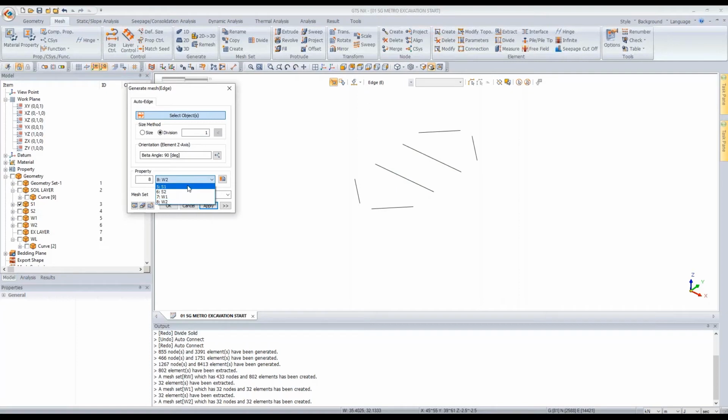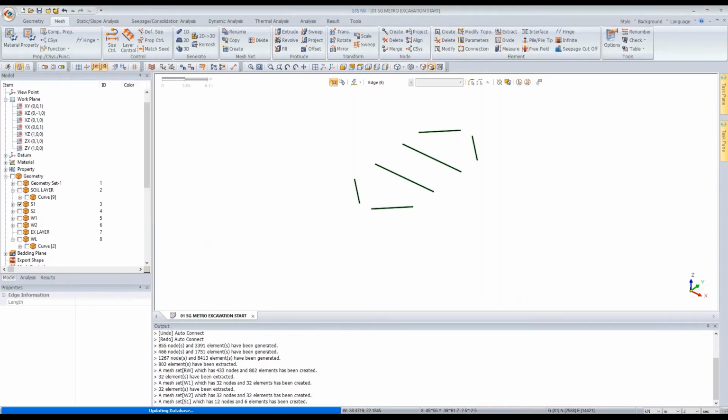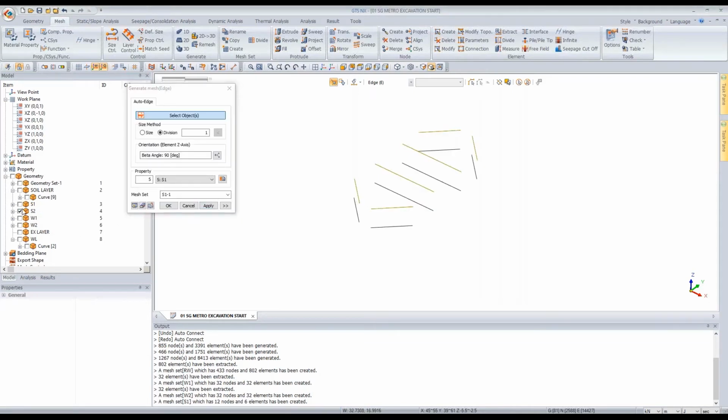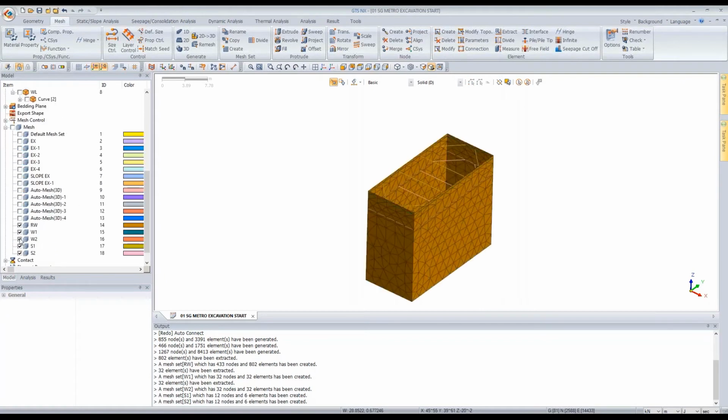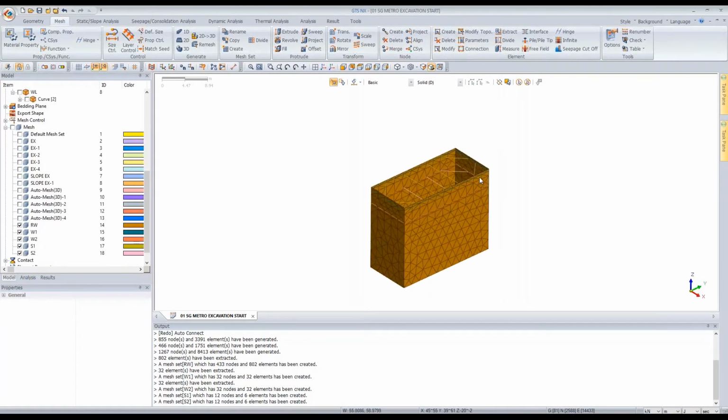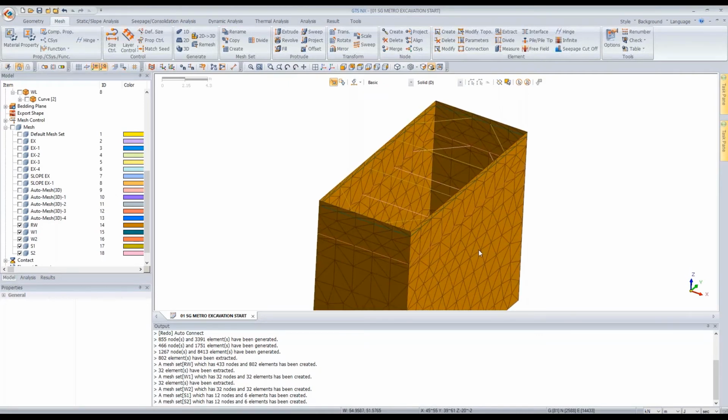And I will select the properties for S1 and give the name S1 and select object, apply, and show the second strut and select all and division 1, mid 1, and select S2 from the property, and S2. Okay, so now I have finished generating the mesh for the structural parts: retaining wall, strut and waler.